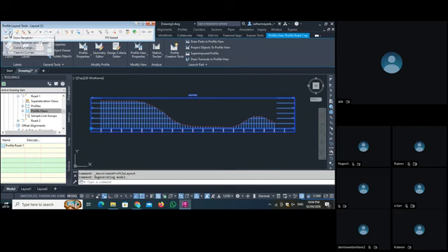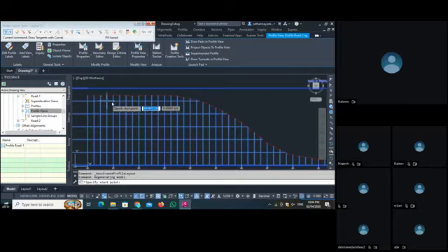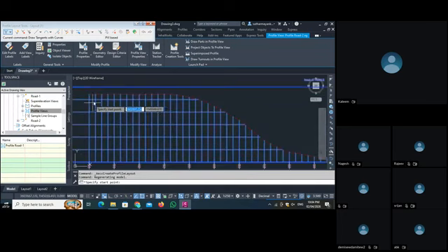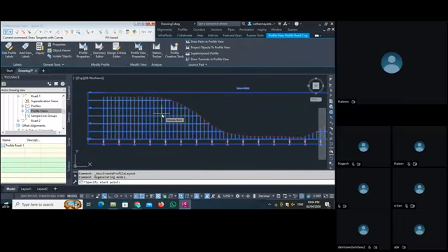No, but are we doing this manually? Will Civil 3D not draft this? Help us draft how the road will go. We have to draw it manually in this elevation. No, actually, what happens, sir? When you are working with companies or with your team, there is always one senior highway engineer over there. They are deciding what is the best area where we go with our design alignment, our design surface. So first they provide a value here, like value number A, value number B, value number C, best fit value. Then they draw the profile. And they check what is the cutting and filling there.